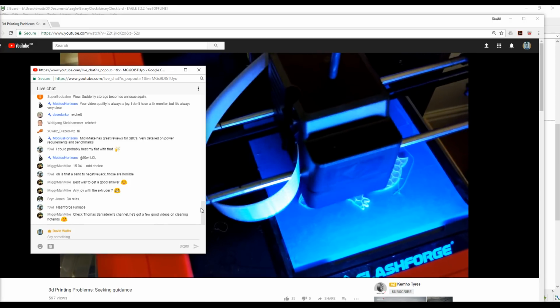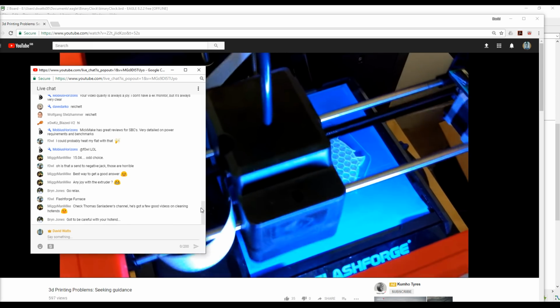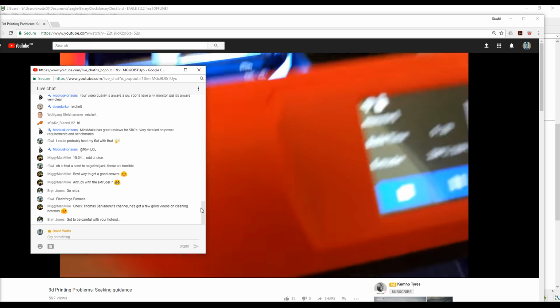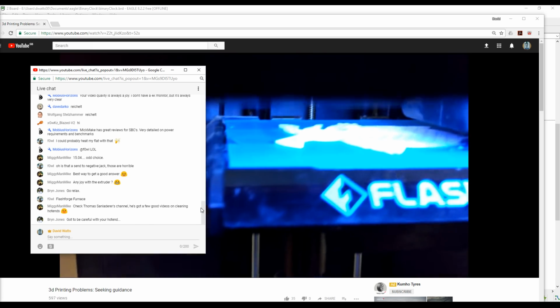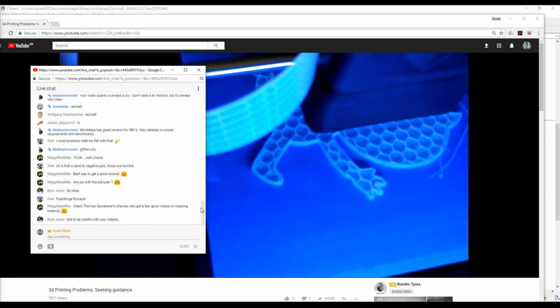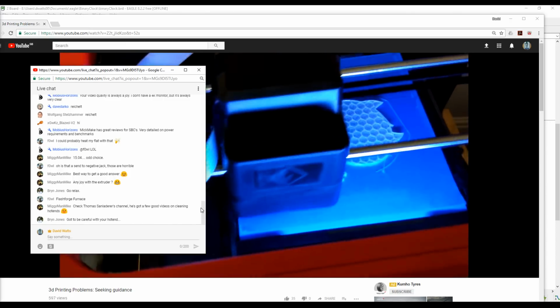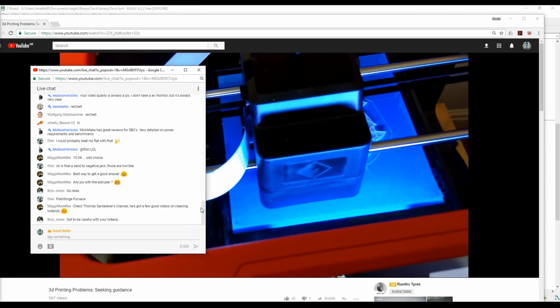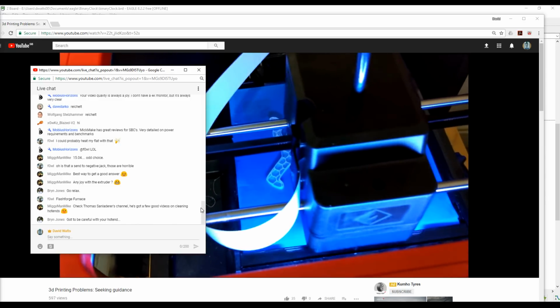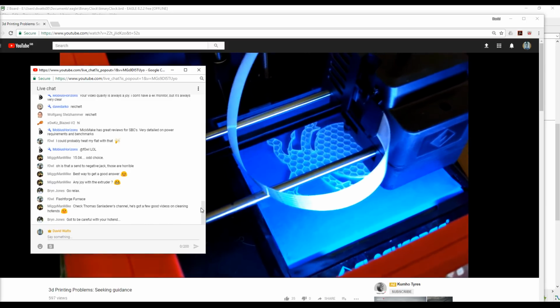But it turns out the filament was pretty crap. I've had that stuff for about 2 years, and it's been inside a plastic box, but for a good few months I didn't know you should do that. So I just left it out in my room, in my little workshop room. So it could have soaked up loads of moisture. In fact, plenty of these filaments could. They have been out once.